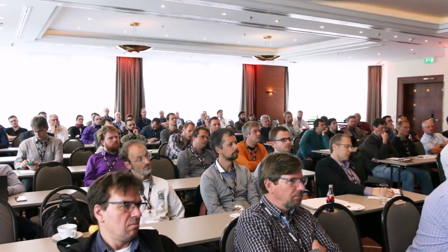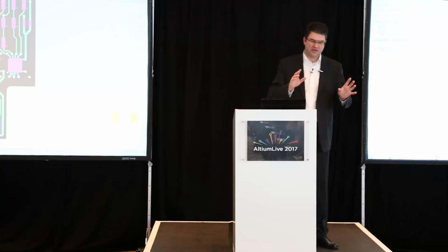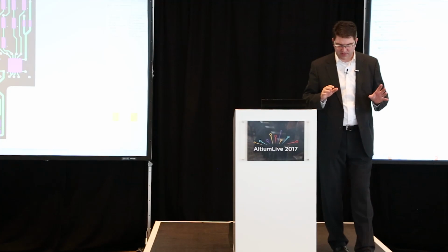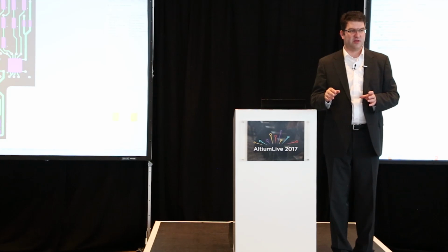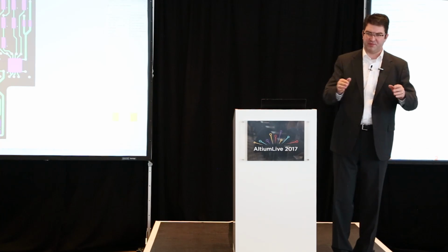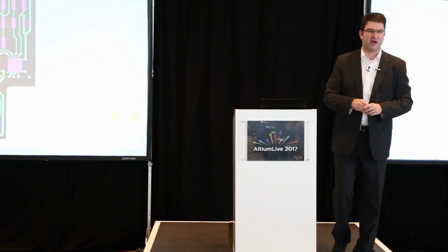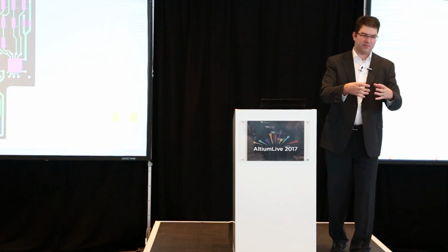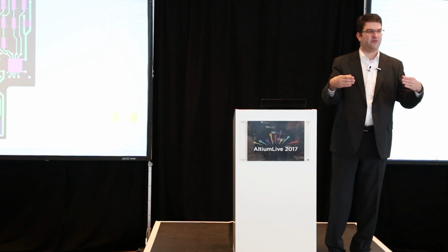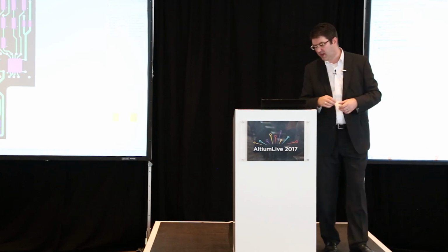Actually, no. You will see that example later on. So there are some restrictions. At the moment, we are tied to 40 to 50% population on the inner layer. We cannot do more at the moment because we still need the resin coming out from the prepregs. But you can populate groups, and those groups can actually be quite big if you know what you do. And we will see this on the next slides.